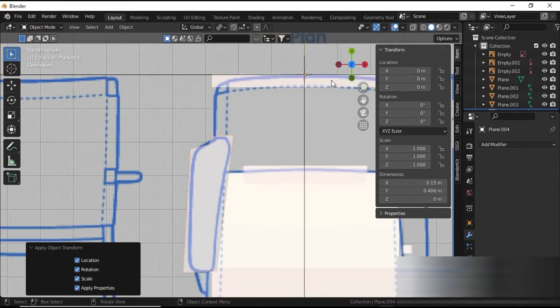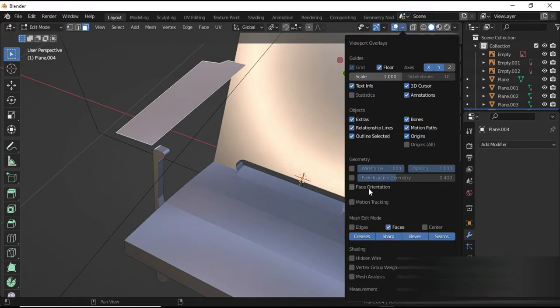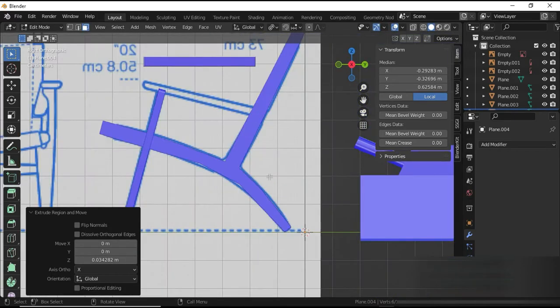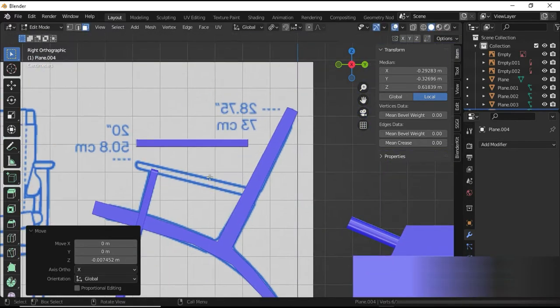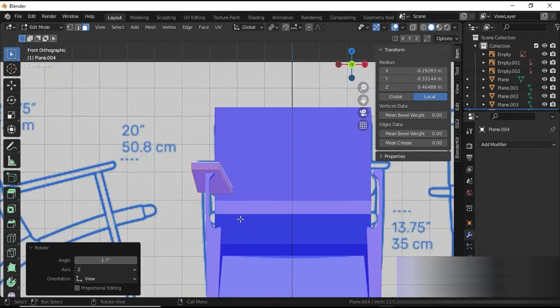It's the same thing: adding a plane and adding vertices, subdividing two vertices, and going to the face tool and extruding on the normal, not on the red side, so that we have no problem. So this is an extremely important check. I've modeled a lot of things, and this is where problems develop.